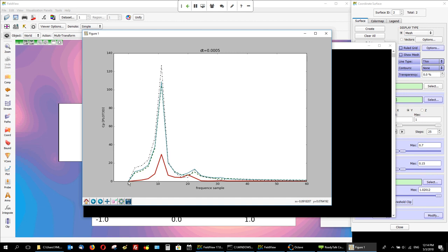The first spike here corresponds to the vortex shedding, really. Again, it's a very simple flow, so there's one frequency for the vortex shedding, and that will also give us the Strouhal number that characterizes this flow. On a more complex flow, you will get more spikes, obviously.